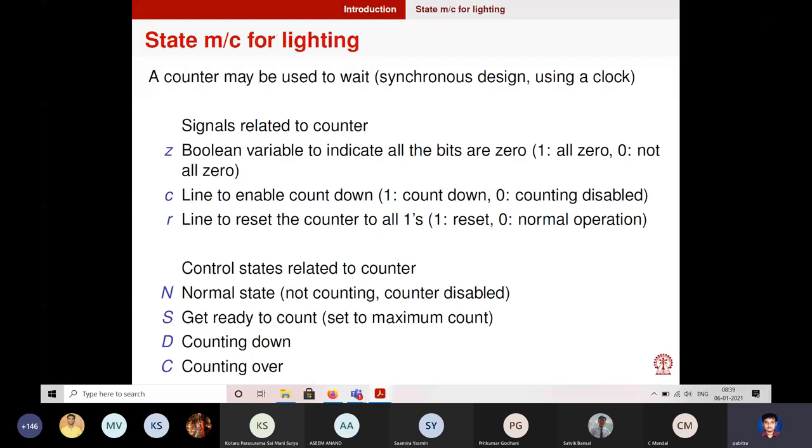What we bother about is that we can decouple this. So your counter will change state only at these time instances. It's synchronous with this clock. Whenever the clock changes, only then you can do something. These have their advantages. You can naturally see that what will happen in between, these problems are no longer there. Everything happens at the clock. Any change happens only when the clock ticks. Is this clear?